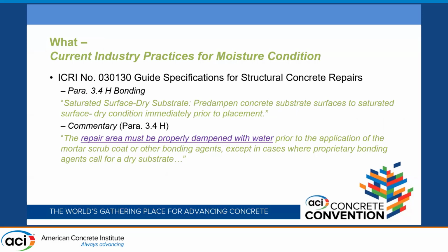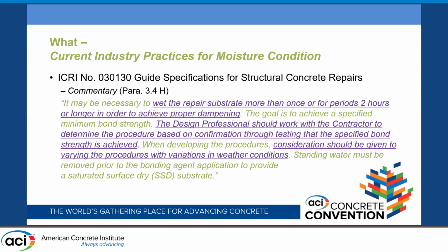There's also more commentary in this clause: the area must be properly damped with water prior to the application of bonding agent, except when a proprietary bonding agent calls for a dry surface. Additional commentary includes wetting the repair substrate more than once or for a period of 2 hours or longer in order to achieve proper damping. They also mention the design professional should work with the contractor to determine the procedure, based on confirmation through testing, that a specific bond strength needs to be achieved. There's a lot more than that, but this is what I'm going to cover here.